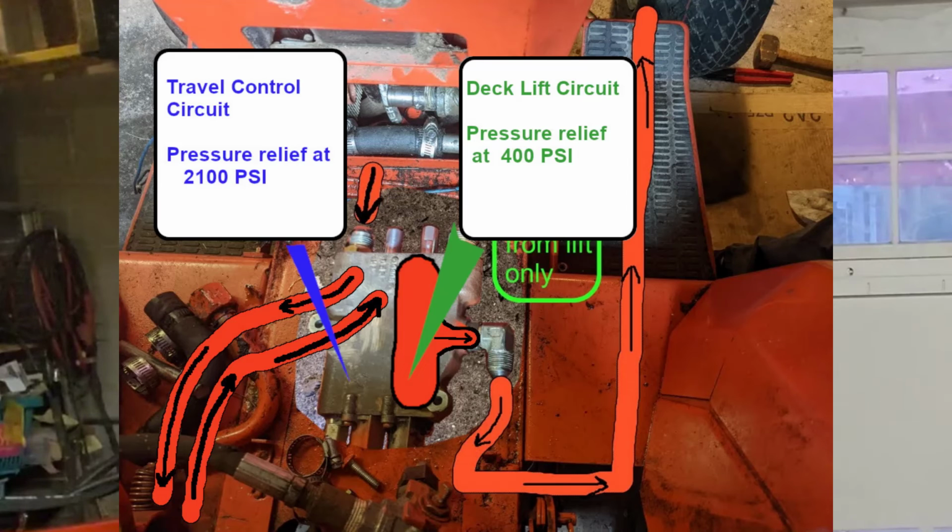Now the tractor travel control valve has 2 different pressure relief valves, one for each of those galleys. The motor galley relief trips at 2100 psi, and the lift circuit relief is set around 400 psi. The deck lift cylinder is fairly light duty and doesn't need to be that strong, so 400 psi is more than plenty for that little cylinder.